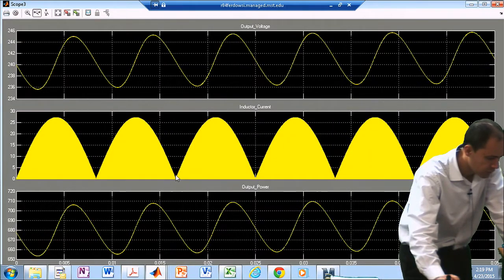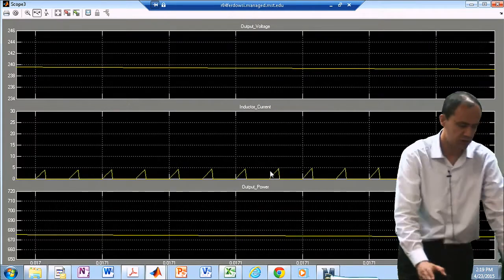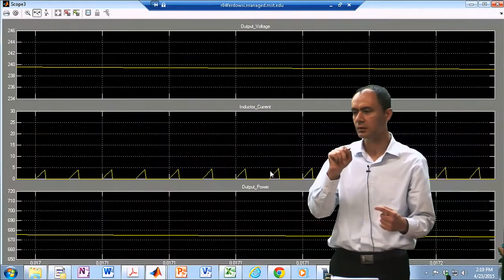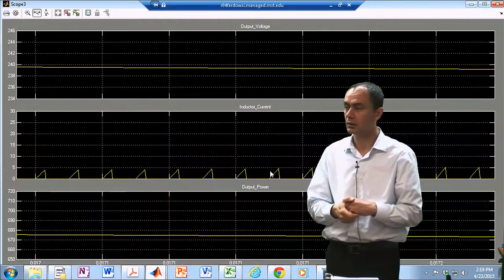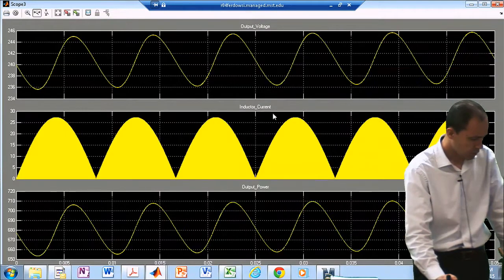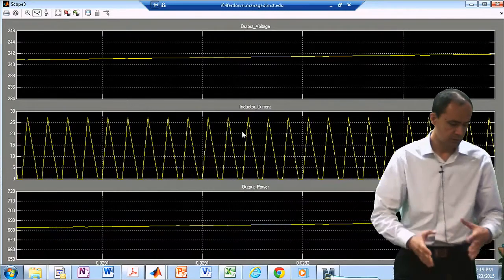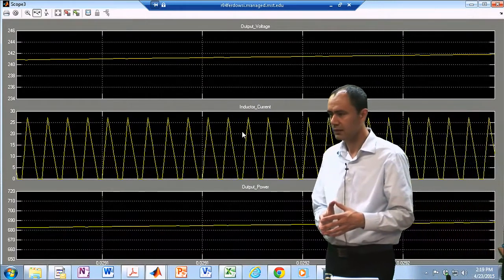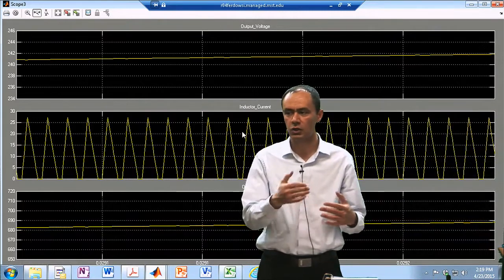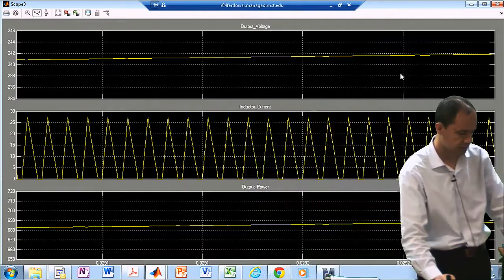This actually, when we are designing the power stage, is when the input voltage is very small. You can see that you only have a little bit of a spike of current, then a long portion of no current at all, and then the next cycle arrives. So if you do not do a good job designing the inductor value, for instance if your inductor is too large, you may actually go into continuous conduction mode. So let's try that.